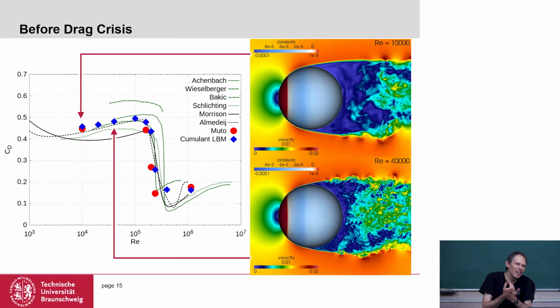a Cartesian grid. On a Cartesian grid, we can resolve the drag crisis. So basically, we can do this with OpenFOAM too, but OpenFOAM uses a body-fitted mesh with extended elements. So what we need as a resolution is to resolve the sphere by 500 grid nodes, but